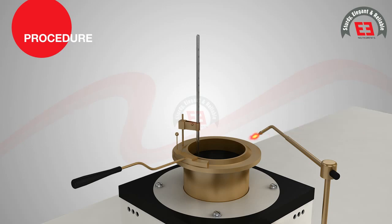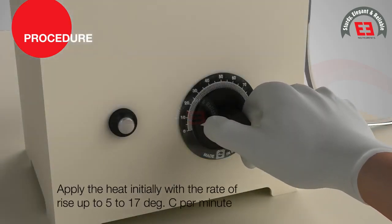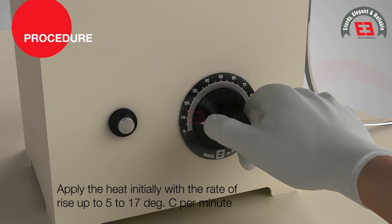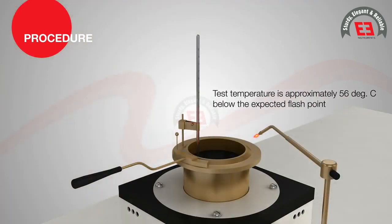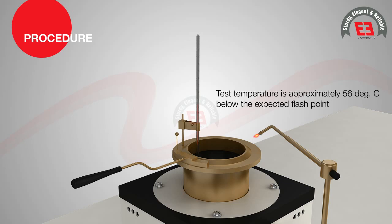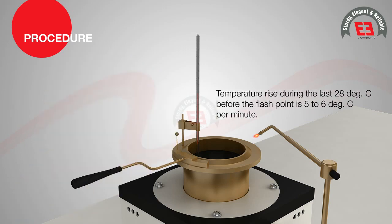Light the test flame and adjust it to a diameter of 3.2 to 4.8 mm to the size of comparison bead. On the regulator, apply the heat initially with the rate of rise up to 5 degrees Celsius to 17 degrees Celsius per minute, when test temperature is approximately 56 degrees Celsius below the expected flash point. Decrease the heat so that rate of rise of temperature during the last 28 degrees Celsius before the flash point is 5 to 6 degrees Celsius per minute.